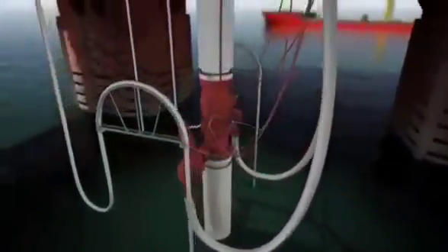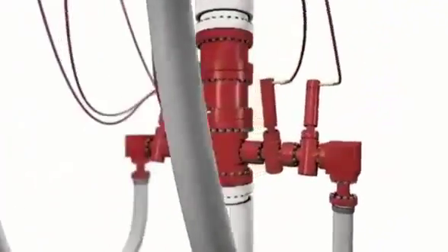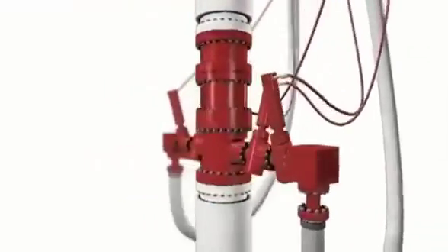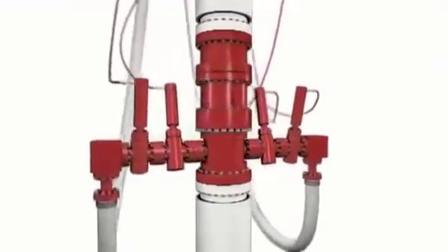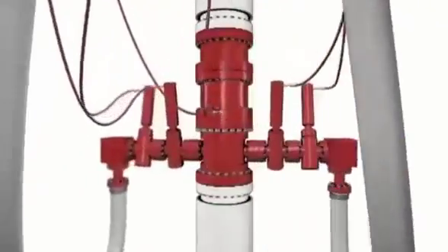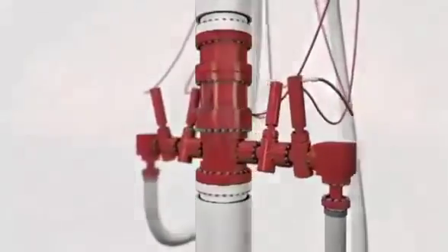Pressurized mudcap drilling first places a column of fluid in the casing, drill pipe annulus. This fluid cap is shut in with a Weatherford rotating control device. The dual element RCD is easily installed and maintained to provide a pressure-tight barrier and diversion capability in the annulus. The fluid cap is kept in an underbalanced state with a predetermined surface pressure of 200 to 500 psi.